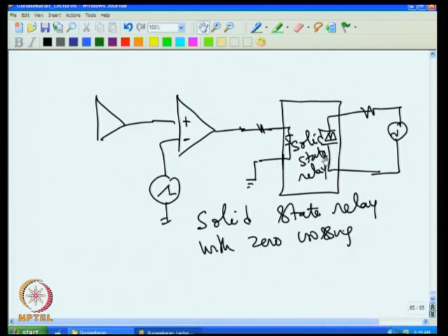So here we had seen today how to produce a sawtooth wave, how to compare it with error voltage and produce a PWM signal, and once PWM signal is obtained, then how to use that to fire a triac with isolation, because we had shown how to use a triac and fire with isolation. Also we had shown how to use MOSFET switch on or off in PWM mode, and then how to give a protection for MOSFET from the short circuit, because if MOSFET or transistor used in the power stage, they must be protected against short circuit.